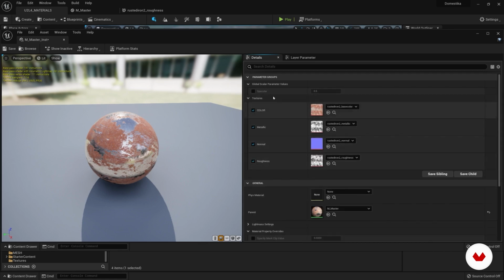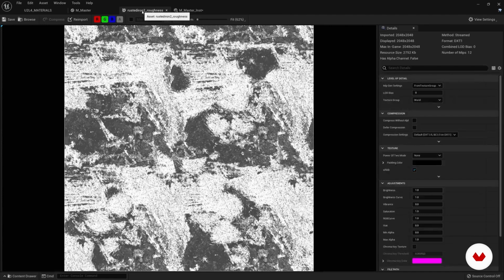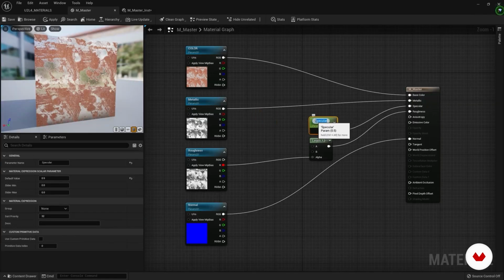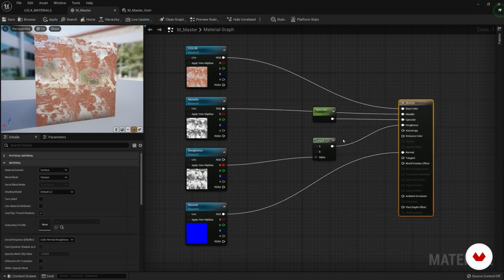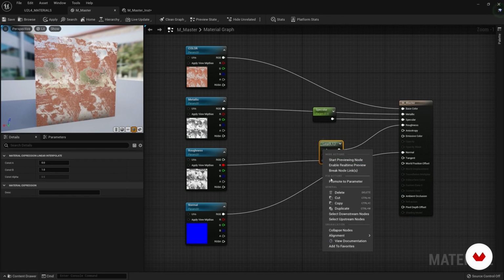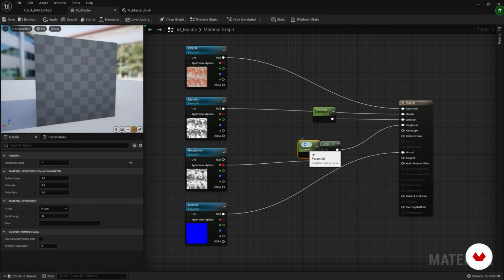Let's reopen the material editor. Specular we had created as a parameter, but we hadn't given it any groups. We also do this other very convenient thing for the creation of a material, and then, later on, we will create our master material with the parameters that interest us. Let's right-click on property A and do promote to parameter.